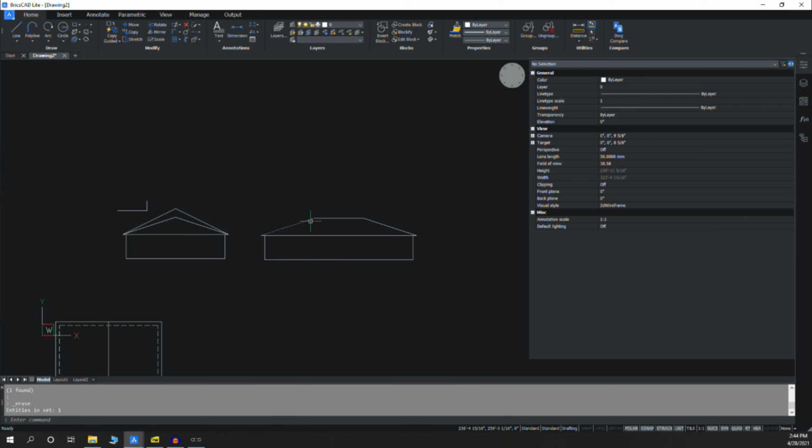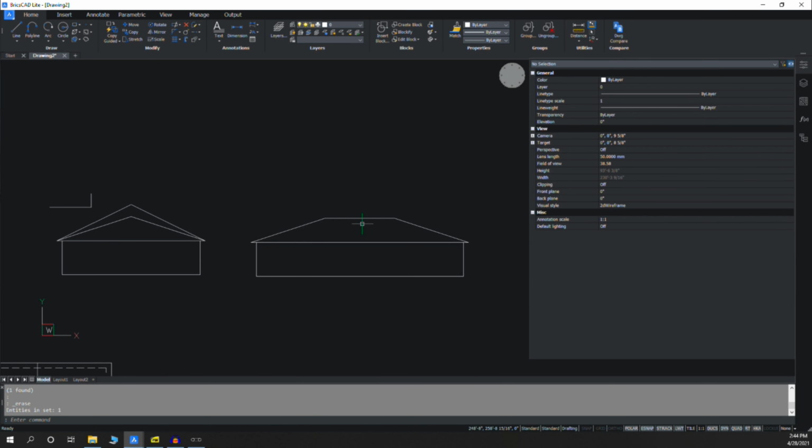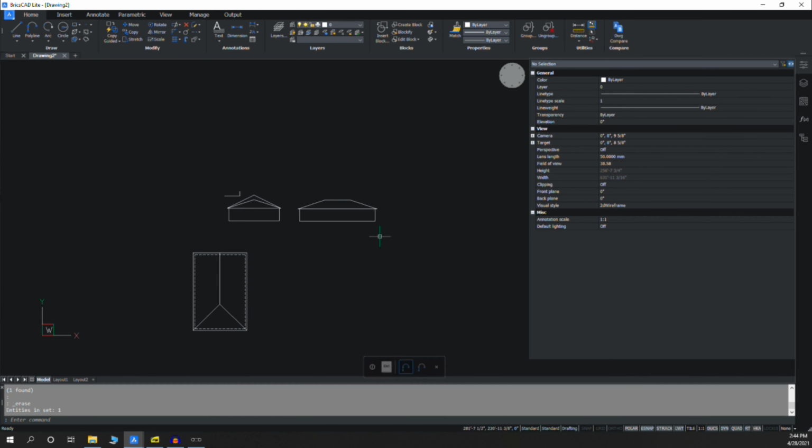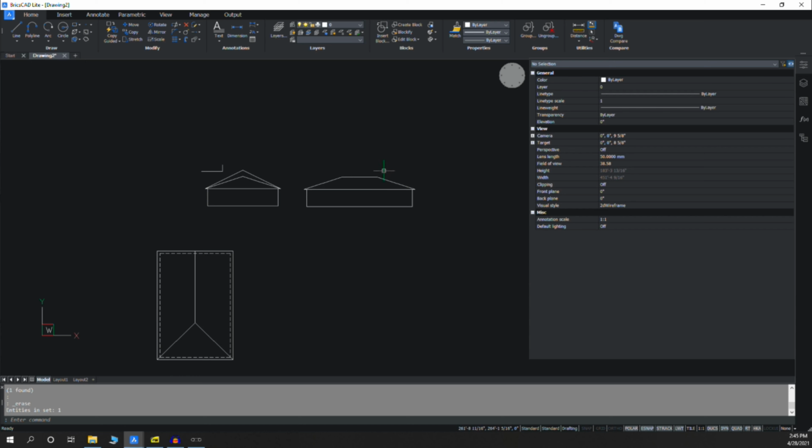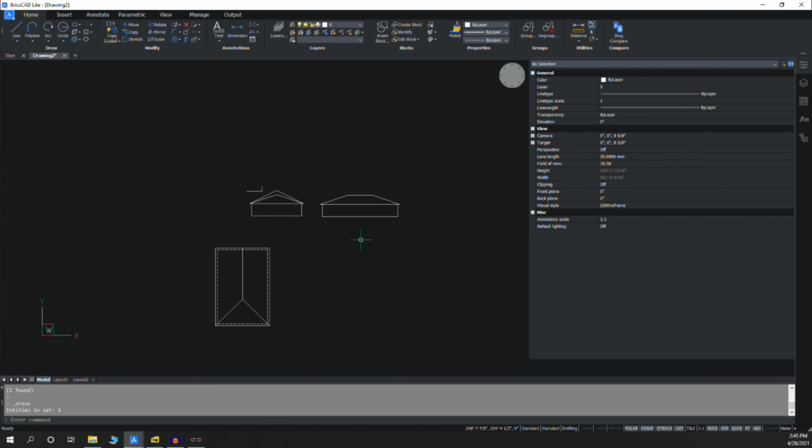As you notice from the elevation view, the angle of the roof is no longer 45 degrees. So that's why it's important to use that measuring stick technique instead of just drawing a 45-degree line here. And that's what I meant by visual math. To calculate that, you can do it with trigonometry, but it's a lot of work and you're likely to get it wrong. This is quick, anyone can do it, and it's spot on accurate.